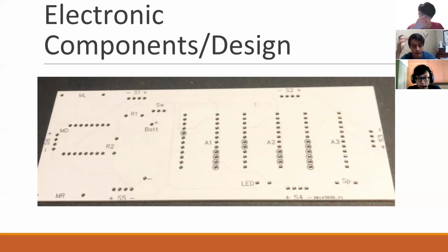Further left of that, you can see where the motor driver PCB goes. Up top and bottom on the left side, we have the motor left and motor right. That's where the terminals connected to the motor drivers go. Back over to the right, near the middle, we have the port for the LED and the port for the speaker. And then there are 6 sensors around the outside, at the 4 pass-through holes that those were soldered into.